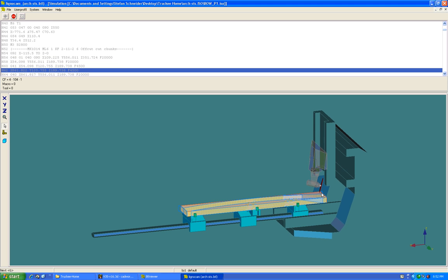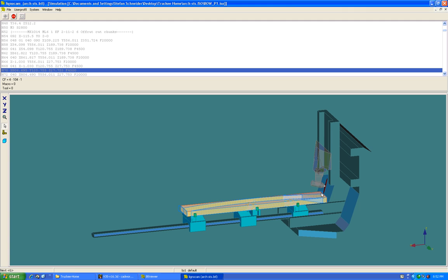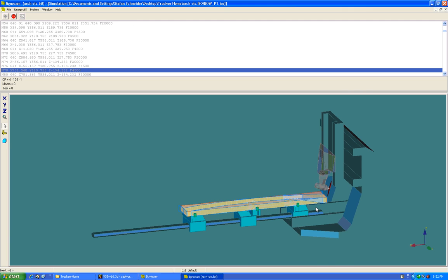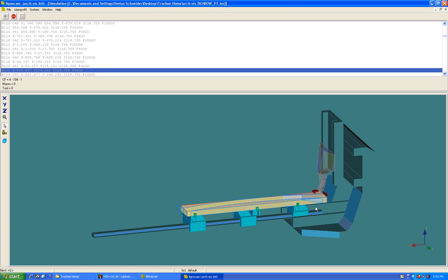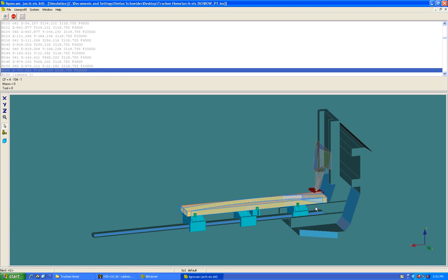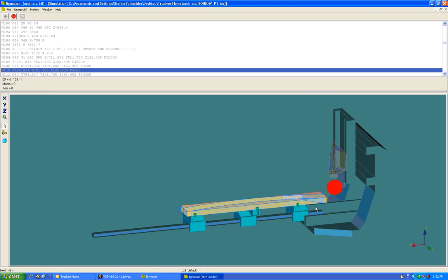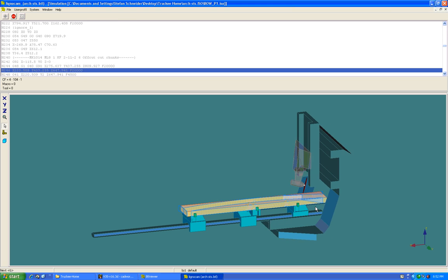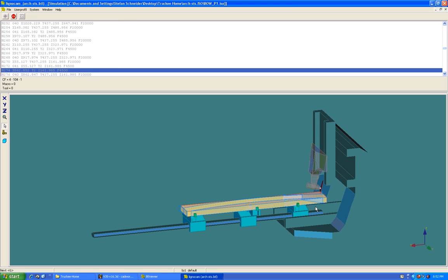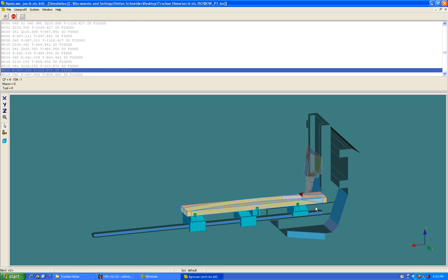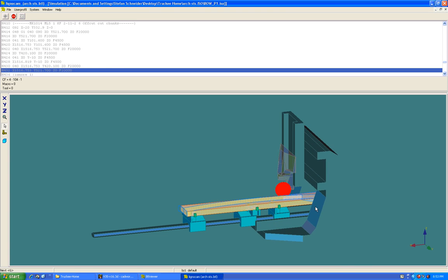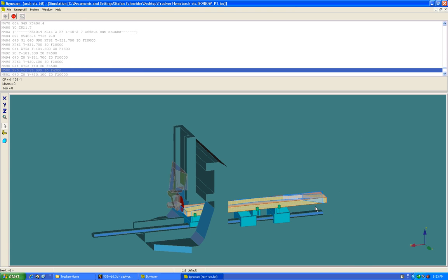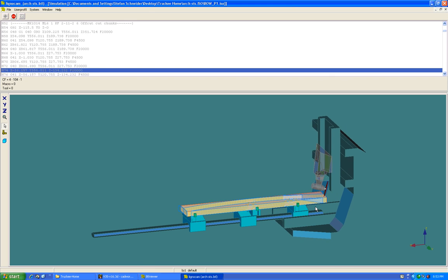We're going to pick the saw and make that bevel cut and angle cut. It has to make it in a couple of steps because the saw blade isn't that big, so we have to cut a couple of chunks at a time. I'm going to run that. We pre-cut everything as much as we can with a saw blade, and as soon as that is done, we go and grab a mill head so we can actually mill the contour really nice and smooth. So that's kind of how that all works.